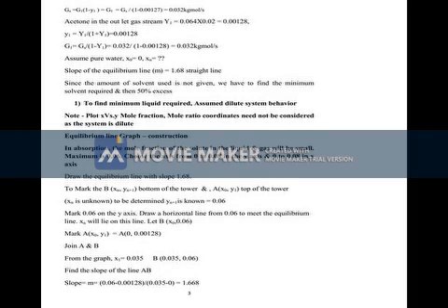Equilibrium data is given. But the amount of solvent is not given. How much water is to be used is not given. So you have to find out the minimum amount of liquid, to find the number of stages, and then you have to take 50% above that.